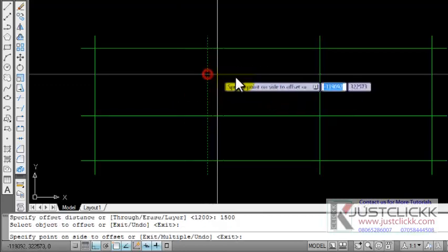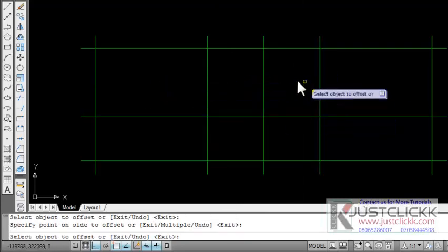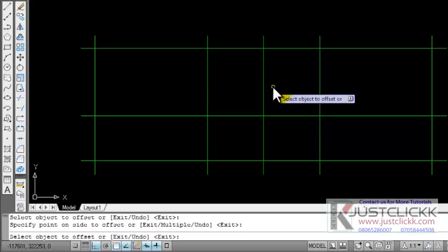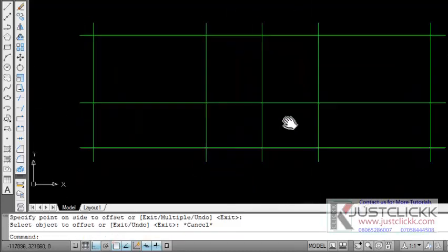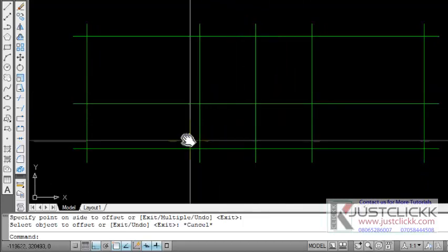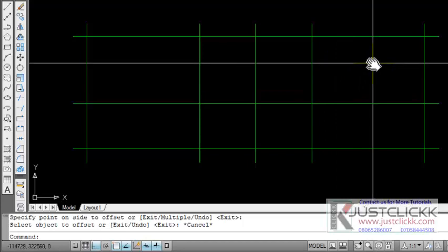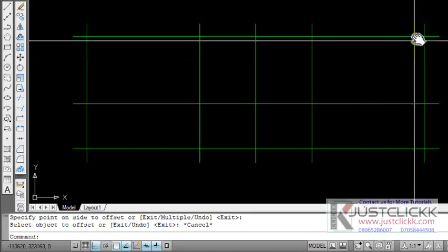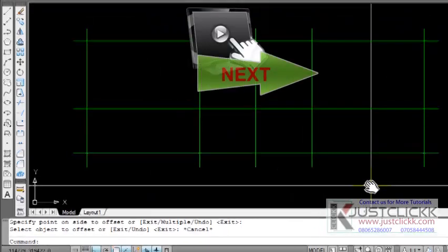So I'm going to partition this to this. So I'll have the toilet here for this office, the toilet here for this office. So I'll press the escape key and I have that established. So basically, looking at my sketch, this is what I have come up with, and precisely the grid lines are established for me. So this is how you can set up your grid lines, and these grid lines are the lines that will be used to dimension the building.